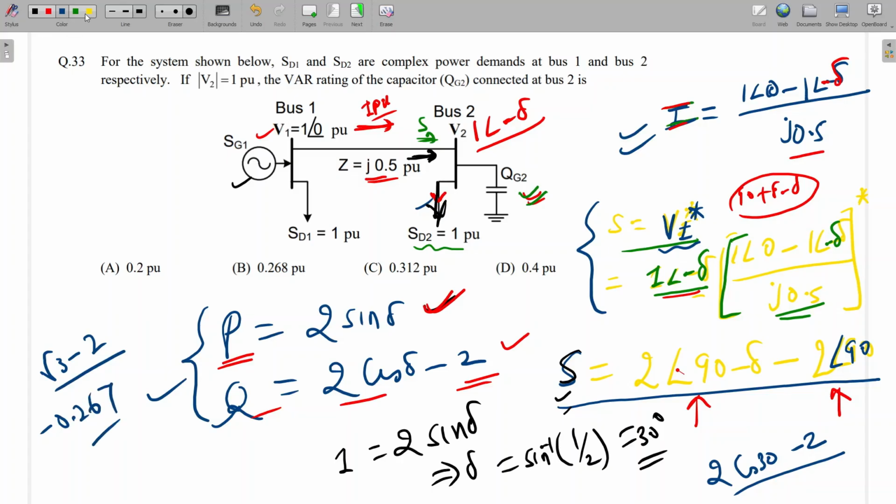Okay. So this reactive power will flow here. If you see here, this is the reactive power. So this value Q is minus 0.267. So we can say that this power is flowing in reverse direction at this node. 0.267 reactive power is here. Since in this direction it is coming as negative, we can say that this power is flowing in this direction, 0.267.